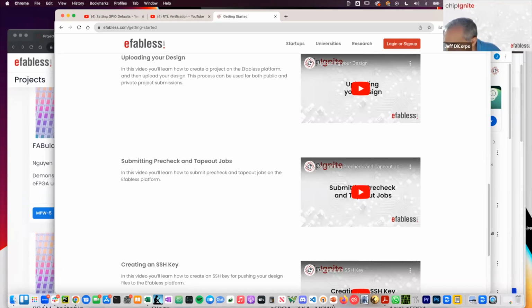Okay, can we implement an RTL which has separate modules like the top module, bottom module, etc.? Yes, absolutely, you can do that. You can decompose your design into multiple modules. The example we just walked through had a top level module and then a separate sub macro. I'm assuming you're asking if you can implement your design in multiple macros. From an RTL perspective, you can have multiple modules and those can all be implemented as a single macro in physical implementation. So both are possible.